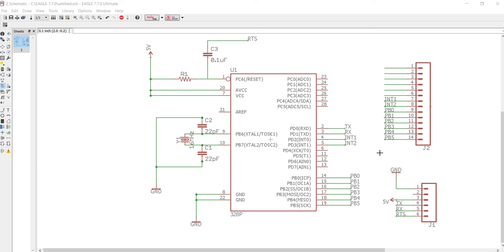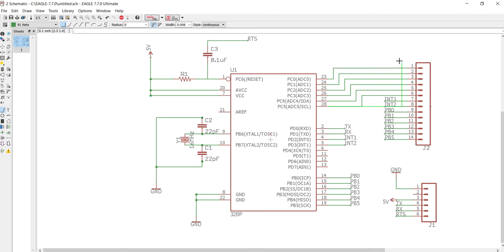Okay, so I got quite a bit of that routed up. I got, not routed, but connections made on the schematic. So port B0 through B5. So you can see 0, 1, 2, 3, 4, 5 here. I also connected interrupt lines, or PD2 and 3, up here. And just to make it a little bit quicker and simpler, up top here, I'm just going to connect all of these lines directly. And this is really more than we need to be doing just for an intro, but oops.